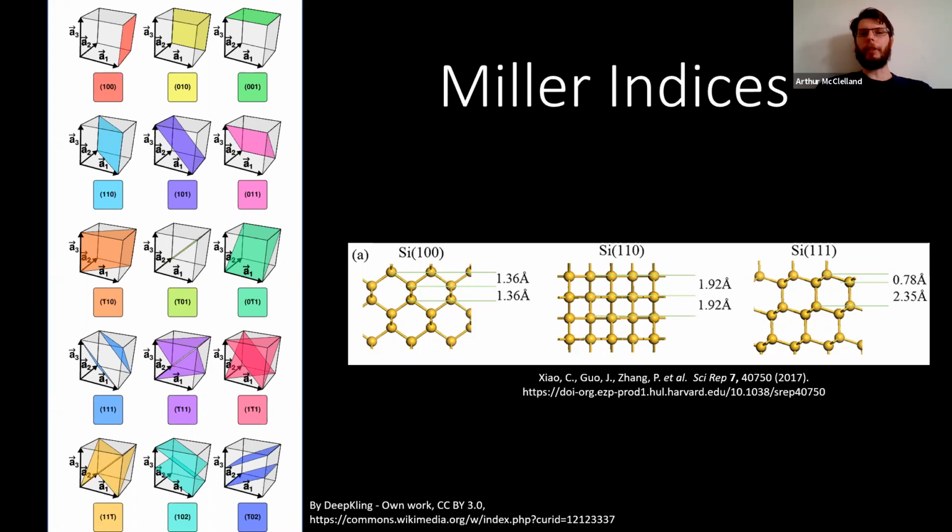And we're going to end up with different etching rates for the different silicon crystals. We're going to see differences in conductance across the different directions, things like that. So understanding the crystals and the crystal faces and the orientation changes the properties of the materials in a significant way.